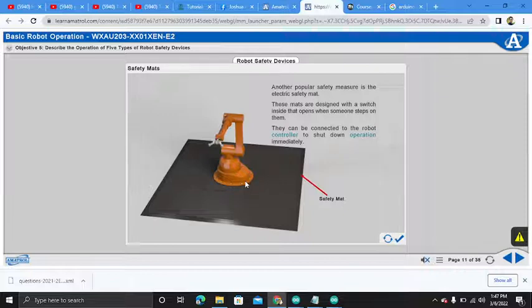So the signs and tape. Warning signs. That's the root word of signs and tapes. You must put up a warning sign and safety tape. The area must be marked off with black and yellow tape to help direct traffic around the hazardous area.